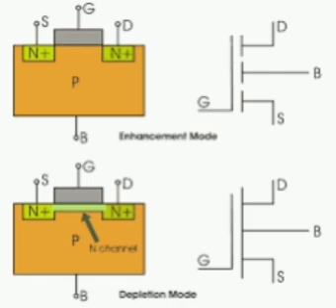The photocurrent of a solar cell IL equals qGLA(W + Ln + Lp), where GL equals optical generation rate, A equals area. Net current of a solar cell I equals I0(e^(V/ηVt) - 1) - IL. The VI characteristics of a solar cell lie in the fourth quadrant, like a quarter circle.